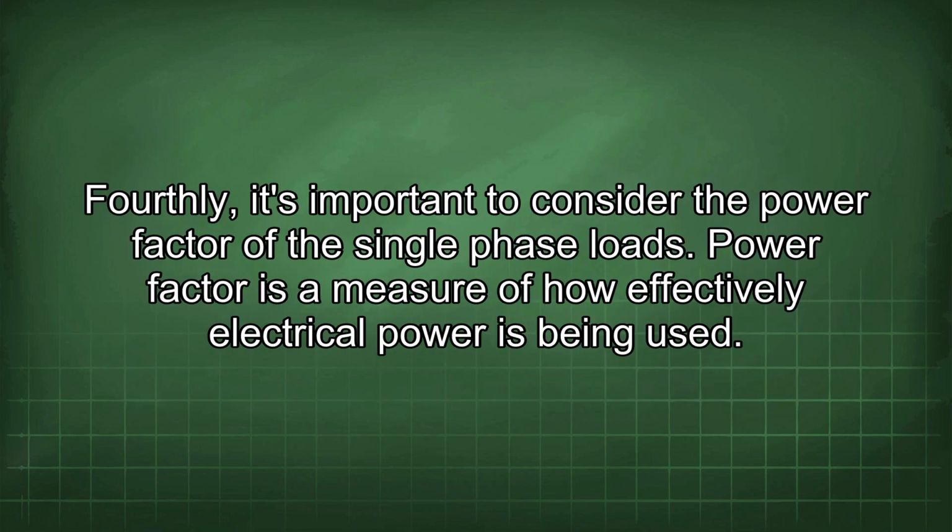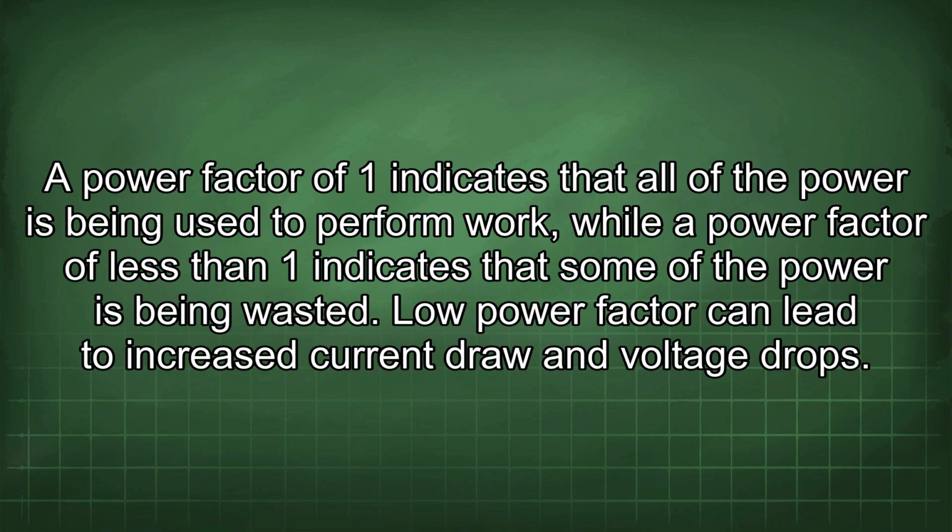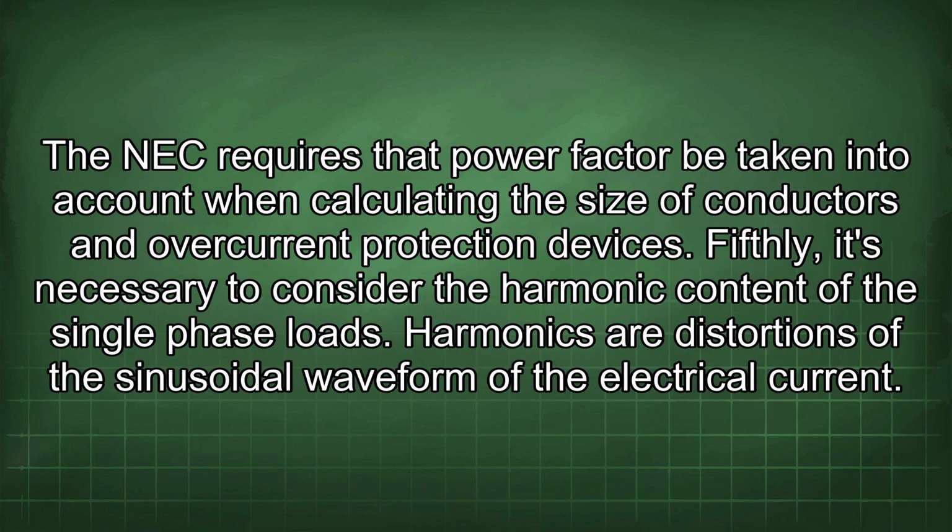consumption. Fourthly, it's important to consider the power factor of the single-phase loads. Power factor is a measure of how effectively electrical power is being used. A power factor of 1 indicates that all of the power is being used to perform work, while a power factor of less than 1 indicates that some of the power is being wasted. Low power factor can lead to increased current draw and voltage drops. The NEC requires that power factor be taken into account when calculating the size of conductors and overcurrent protection devices.